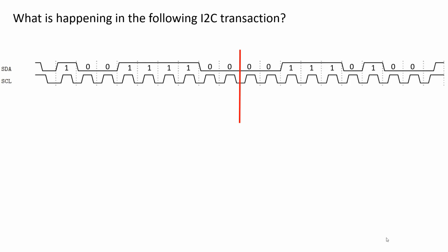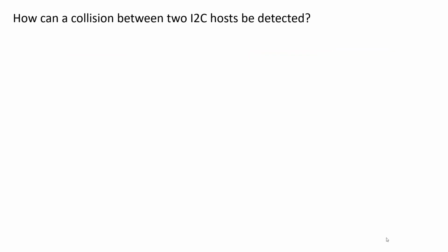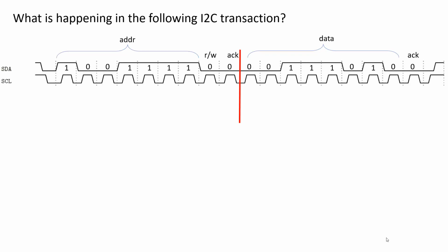And so after the first 9 bits, you can kind of draw a line there, and then we have the address, the data, the ACKs, and then that read-write. You've got to always remember that read-write bit is the 8th bit in the header in the first 9. Anyway, read-write is 0, so you're writing, and the address is 4F, writing to 4F. Acknowledgements are both 0, that's good. Data is 3A. And again, you're reading left to right, most significant to least significant there.